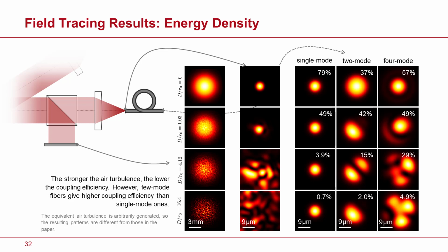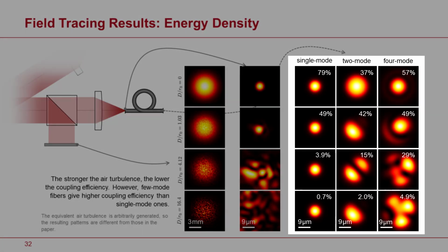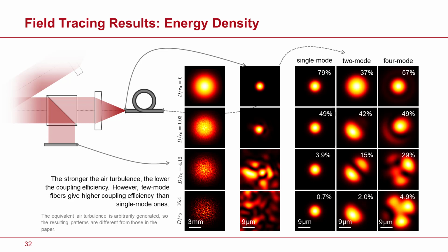And then, as I said, 4th and 5th. Sorry, I said 6th before. 3rd, 4th and 5th columns correspond to the results after propagation also through the fiber, and superimposed on the different fibers that were investigated: single mode, 2-mode and 4-mode. And superimposed on those results, we can read the values of the coupling efficiency, which have been calculated with that new detector.